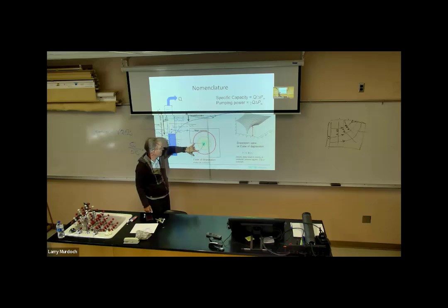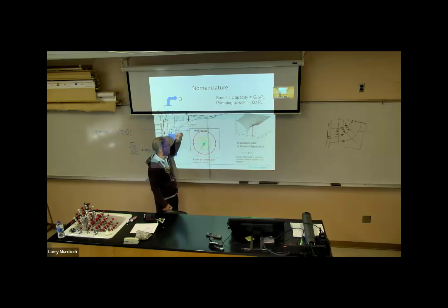And in order to have the ratios stay the same, the spacing between the contours has to decrease as the well is approached. Hopefully, on the flow nets that you handed in, that was one of the characteristics that you found, that this spacing has to decrease as you get closer to the well.